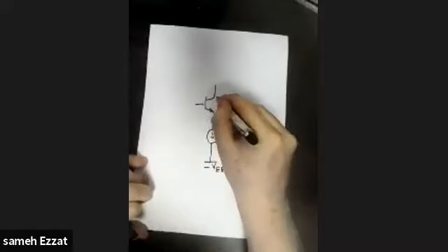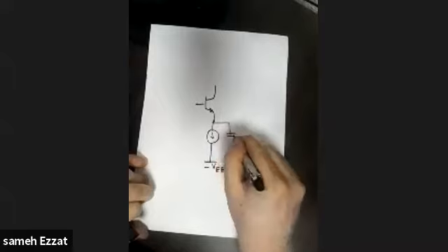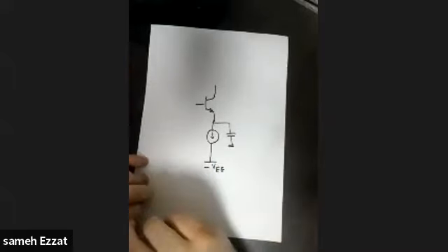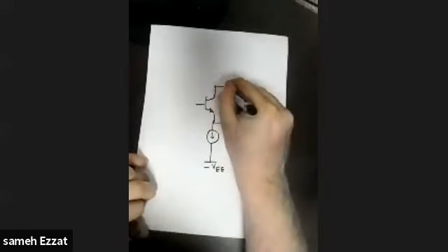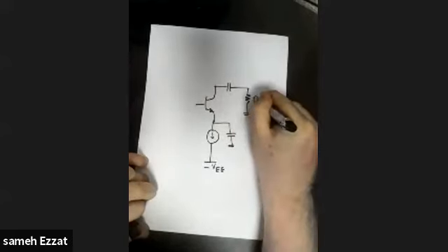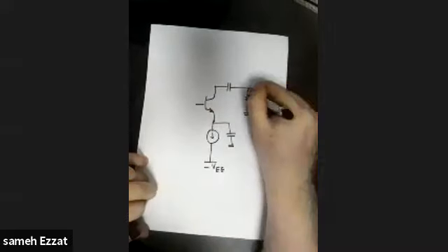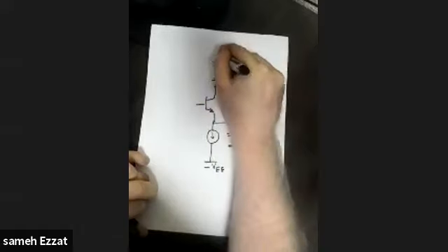And here also we have a capacitor. In the collector terminal, you have first a capacitor, and then you have the RL, or the load resistance, and this is the indication for the output. And also you have another resistance RC connected to VCC, which is another DC supply.